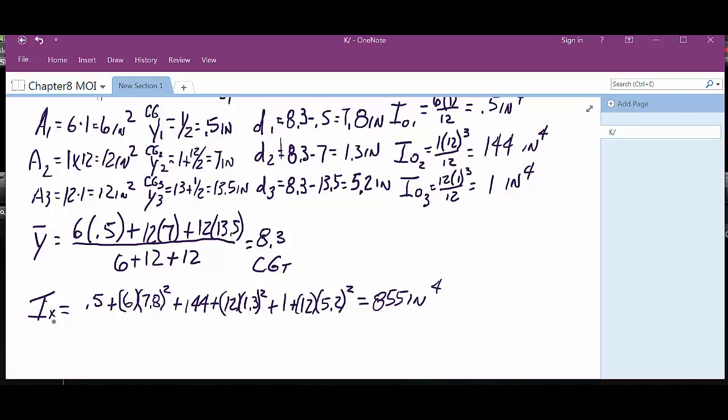If it's symmetrical, there's no difference between the distance this way on the individual components as opposed to the overall component. So if that distance is 0, then that negates that whole second part of that equation. So then all you're dealing with is the moment of inertia of each of those individual pieces. It actually becomes easier. Yeah, it's much easier at that point.